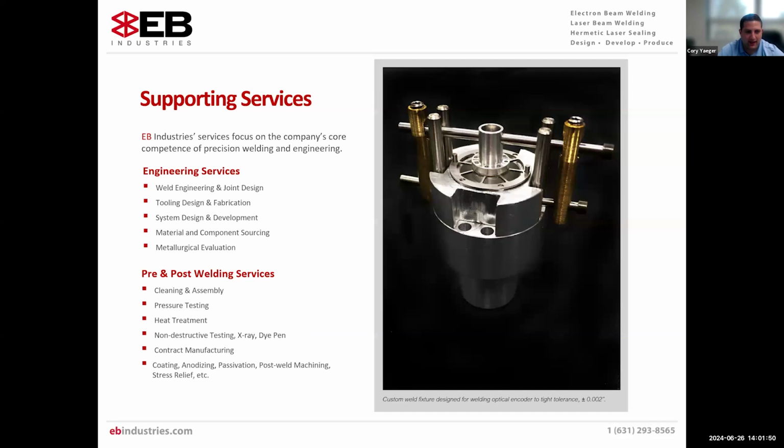Dom, one thing I was going to add as well is that electron beam welding has an incredibly higher rate of efficiency with the energy you put into the part that is able to be absorbed by the part. Lasers typically have a challenge with welding reflective materials, things like aluminum, copper, titanium. With an EB welding process, the majority of the heat you're putting into the part is actually being retained by the part, partly because of the vacuum chamber we're welding in.